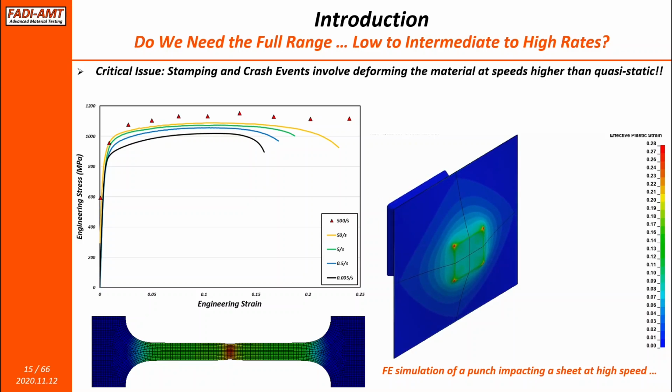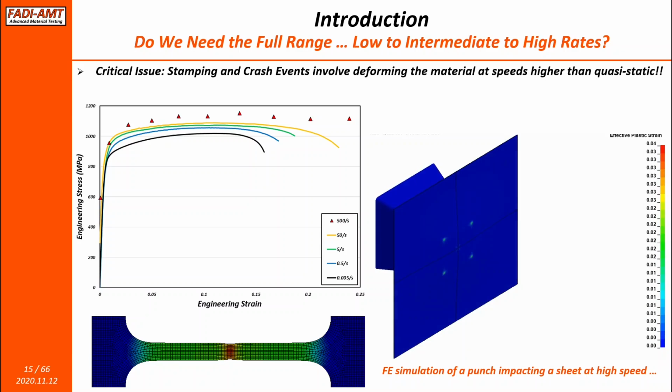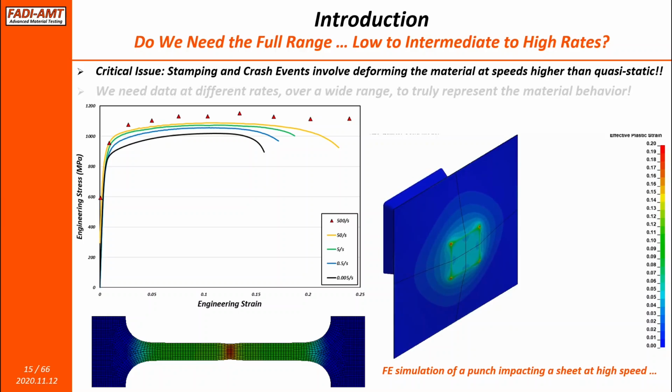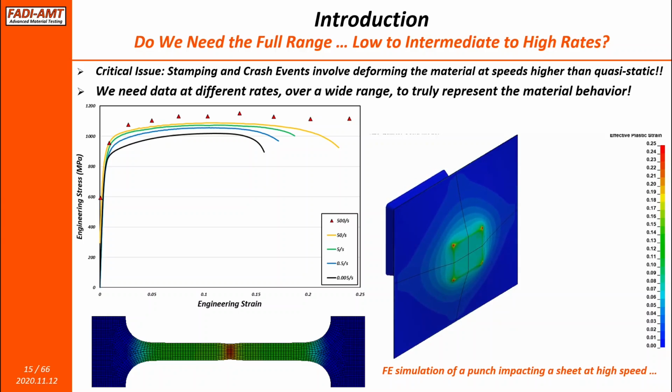Therefore, to execute this simulation correctly, I have to provide a sufficient number of curves that describe the behavior of all the elements here. And that's another reason why we typically talk about not one single curve at a particular speed. We typically talk about several curves to cover a full range of strain rates that describes the entire event or the entire process.